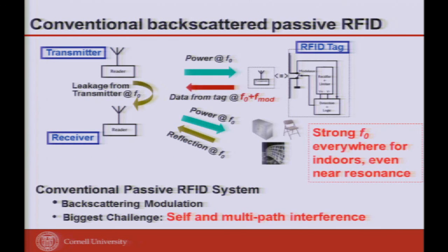Okay, so conventional backscatter is just showering the tag with the fundamental wave, and the tag backscatters with modulated information. Okay, so for sure there are main interference paths from any objects in the room, especially metal or ground. That's reflecting a lot, and many times this is much closer than the tag. So you can imagine these reflections are very strong. Many times, if the frequency is high enough and your radiating power is enough, your room can be in resonance. That means all phase information is lost.